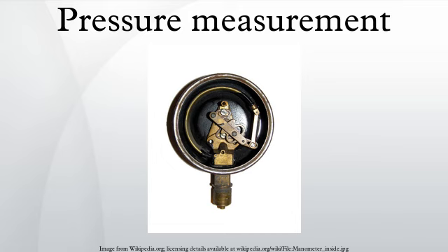Because pressure was once commonly measured by its ability to displace a column of liquid in a manometer, pressures are often expressed as a depth of a particular fluid. Manometric measurement is the subject of pressure head calculations. The most common choices for a manometer's fluid are mercury and water. Water is non-toxic and readily available, while mercury's density allows for a shorter column to measure a given pressure.